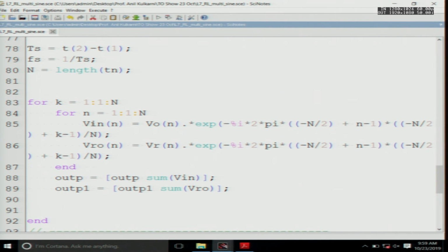So, you can actually evaluate this using the formula which is shown here. Using discrete samples, we evaluate this integral. The integral becomes a summation over one period. Okay. So, once it reaches steady state, we actually get the Fourier components. Remember, we are doing this numerically.